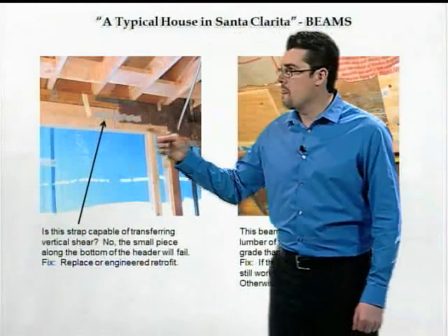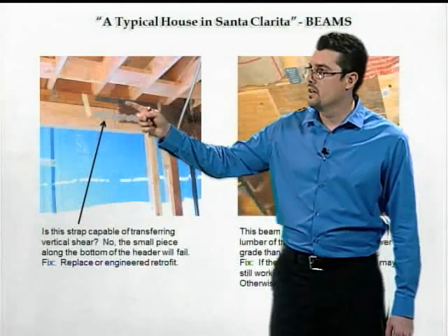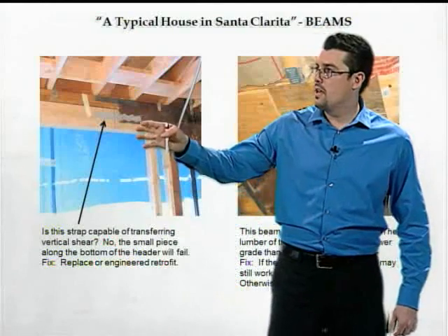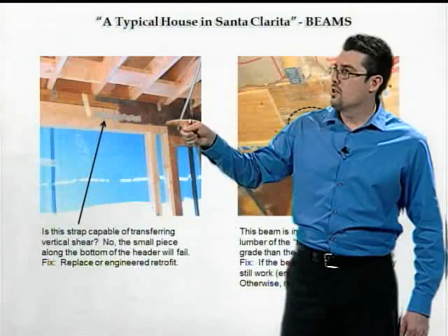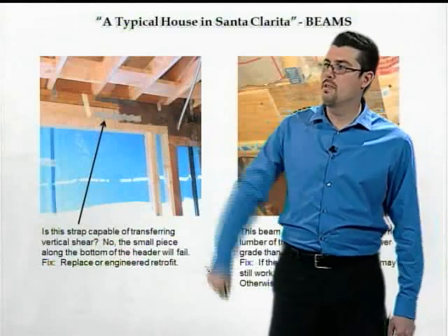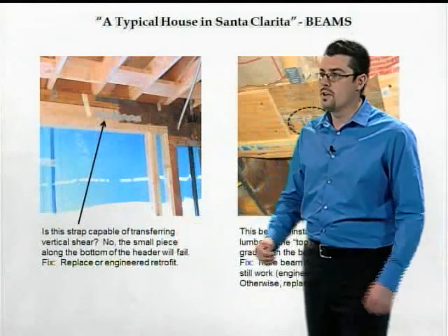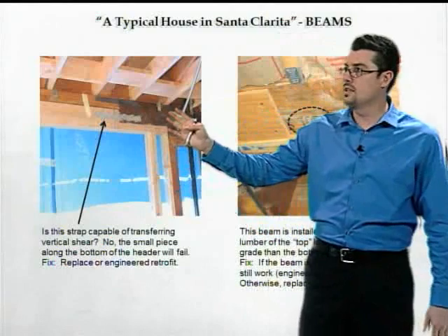Next example here is you've got somebody went ahead and cut an existing header right here, and they framed a new header in, and it doesn't run all the way back to the support. So they just put a strap in there, a steel strap. Is that strap capable of transferring any of that vertical shear? No. I mean, this does not comply.